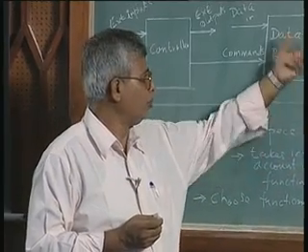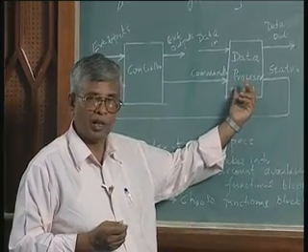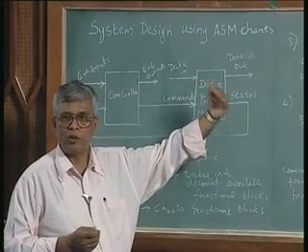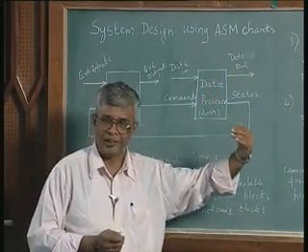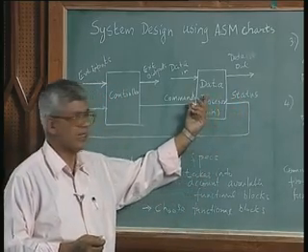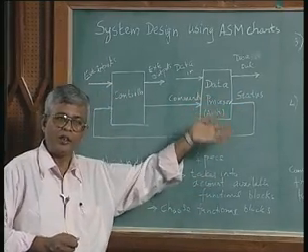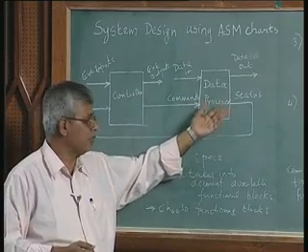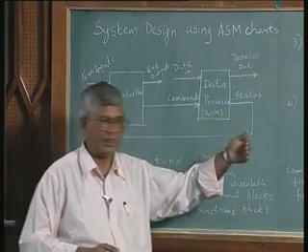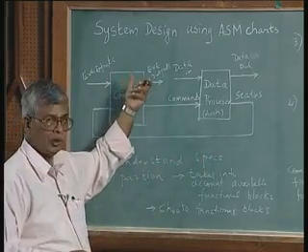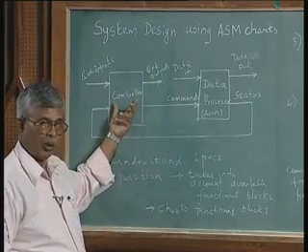So you identify the processor functional blocks, clearly find out whether they are capable of delivering the goods in terms of the data processing that is required, that is the ultimate goal of course. But also identify the command signals required to initiate or activate each of those functional blocks, and identify the status signals that each of these functional blocks will give at different stages. Take those into account along with the external inputs and outputs to design your controller.